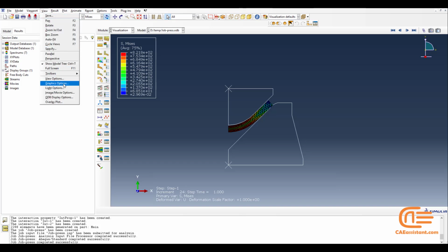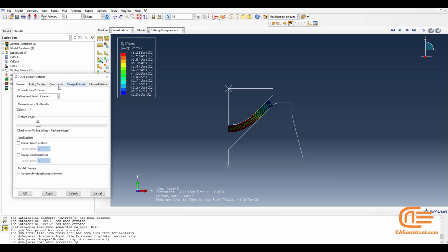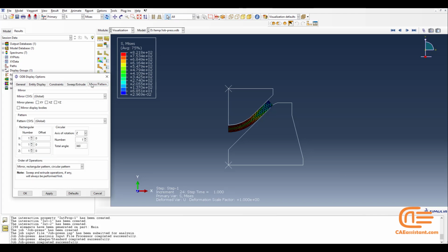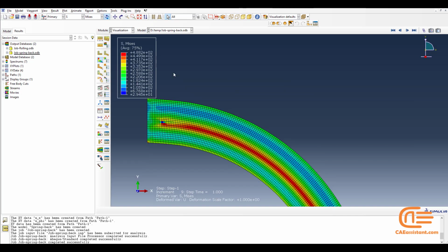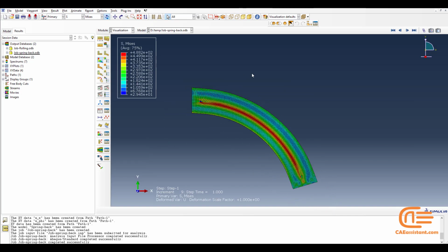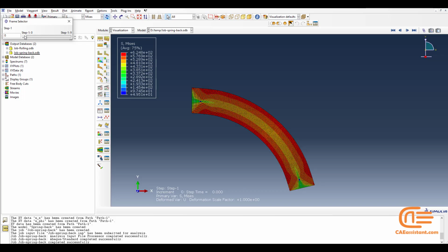It refers to the reshaping of metals into desired forms at room temperature. It suits well for parts requiring high precision and a good surface finish. While cold forming offers many advantages, it is important to consider the potential for residual stresses within the material. The residual stresses in cold-formed components can influence their behavior, potentially affecting the quality of the final product. Experimentally measuring these stresses can be challenging.